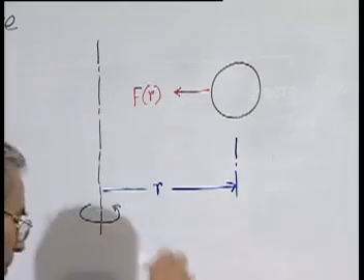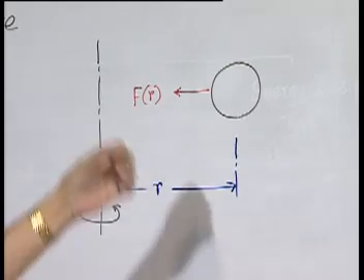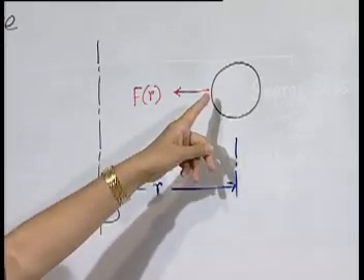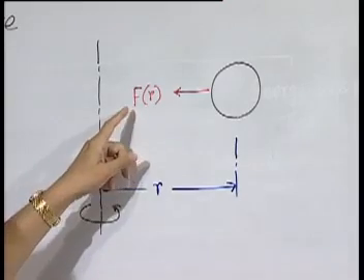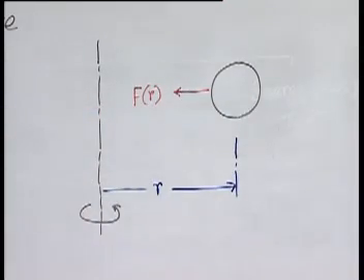This is the resultant effect of gravitation, the tension in the link, everything together. It can be considered equivalent to a radially inward force, which is the restoration force for this whole system, and we call it the control force.